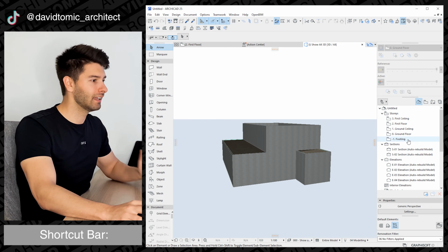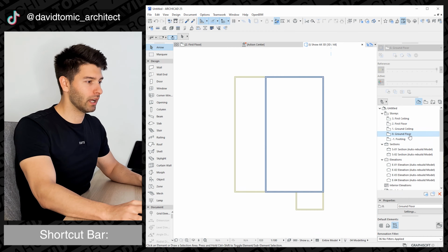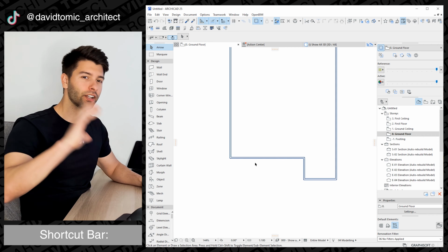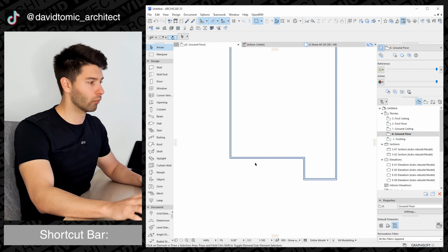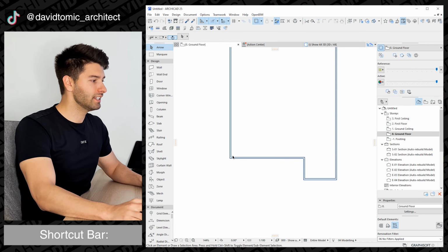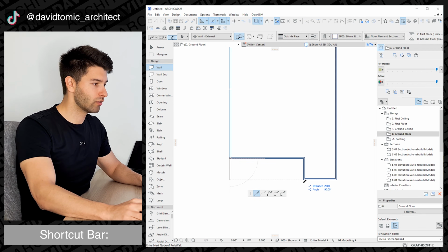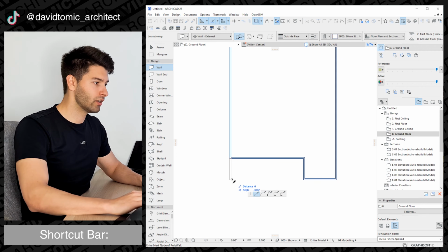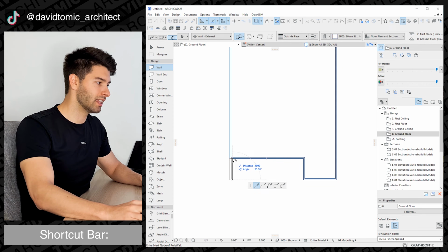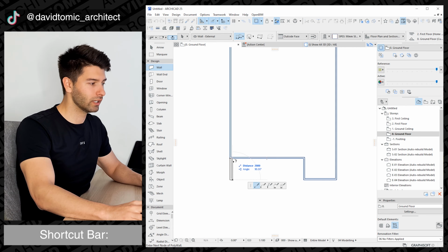To be able to create that, let's start by going to our ground floor, and I'm basically going to create a wraparound floating roof effect. Now, the easiest way to create this is simply by copying this wall across, dragging it out to the edge, and we're going to make this 250 millimeters thick because that is how thick our floor is above.